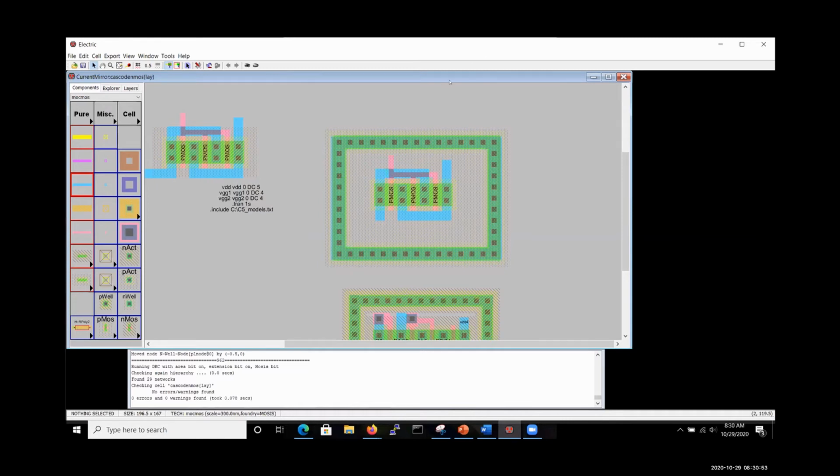So I think that PMOS guard ring can probably be smaller. The issue that I was having was that I forgot to make it NWell all the way in that region, a giant thing of NWell for everything to sit in. The issue it was having is it's effectively saying, you have this piece of NWell over here, and it might be at a different potential than this other piece of NWell, and the width of the P well between it was too small. But if you make the whole thing NWell, it's like, oh, I understand what's going on now. Great, thank you. Yep.